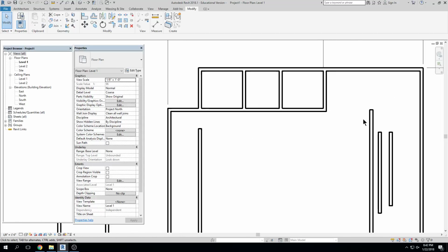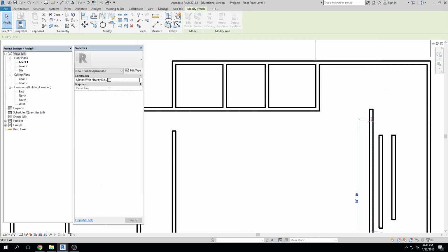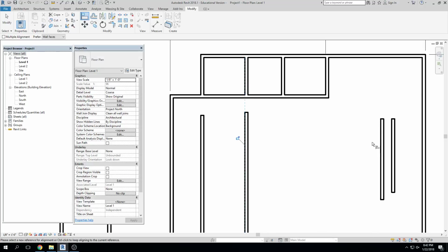Okay. So next line here. I'm going to align this object with that one. AL, align, click, right? I established that datum. Second point, click, and they align. AL, click, click. And this is one thing that I don't like about Revit.